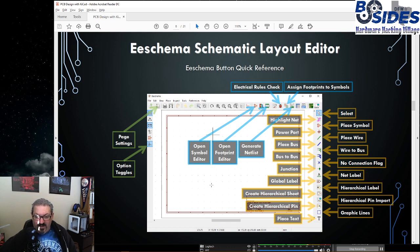So if we have, let's say, a 5-volt connection coming off of a microcontroller, and it's got to go to several things, like an LED or a resistor rather, and something else, rather than have multiple lines crossing different components and going there, off the microcontroller, we might use a global label that says 5 volt, and then on each of those component pins, we'll put that same global label saying 5 volts.